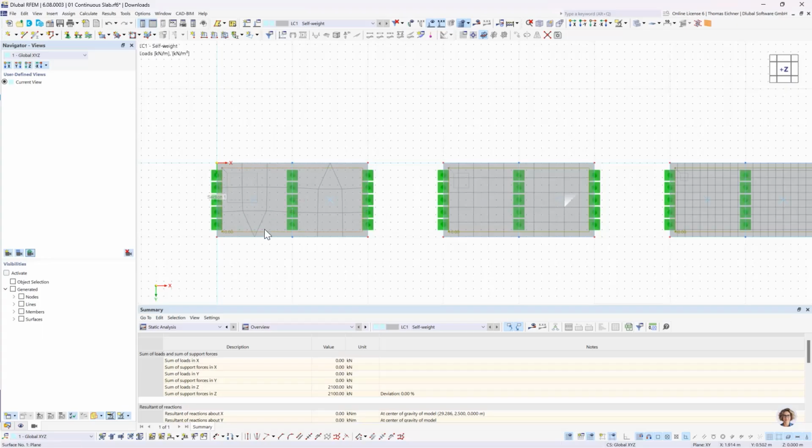And that's the point here in the next figure. We can see 5 elements here. I learned some rules in my studies, and the rules were like 6 elements between supports for a single span beam should be good.